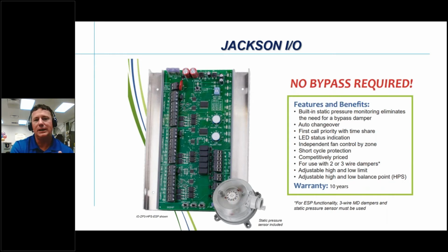Because if we're talking on a legacy system that's using a variable speed blower, if we can control that ductwork and try to maintain our external static pressure very consistently, it's not going to affect the speed, the RPMs of our variable speed blower. And that's really what we're going to have to start focusing on.